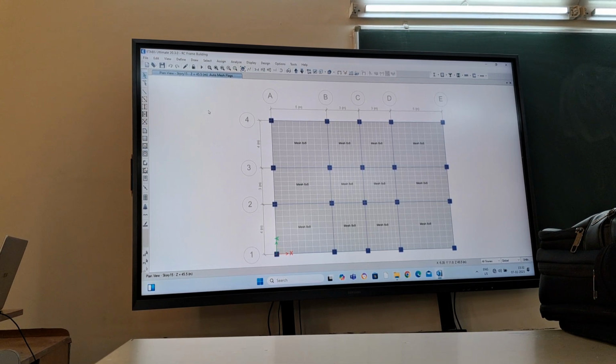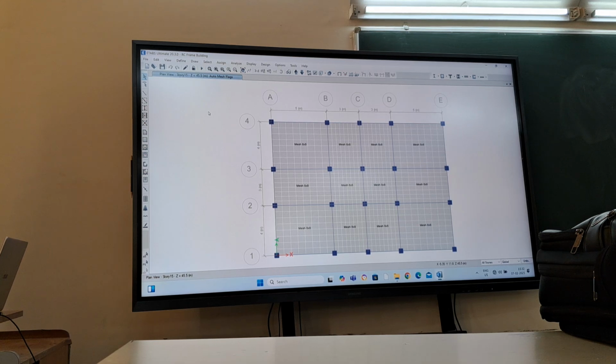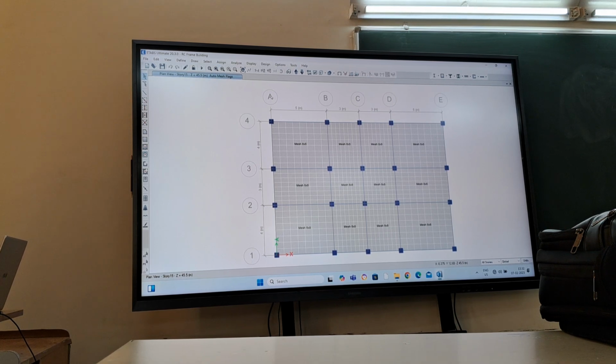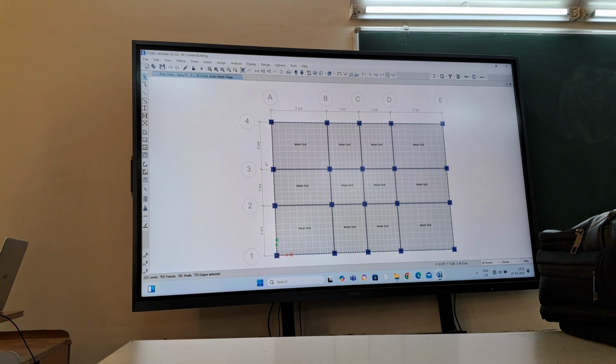So now it depends on what you are trying to model. Same kind of element. By looking at this, you cannot understand whether rigid diaphragm will be required or not. That as a designer you have to understand. Now in this case, since we are modeling the shell element, we have to define the rigid diaphragm also, and that you can do by selecting the entire model. Select this one, and you have two options. One is using the area definition, another one is using the joint definition.